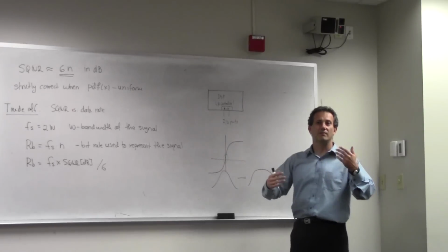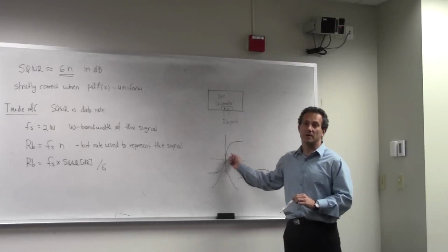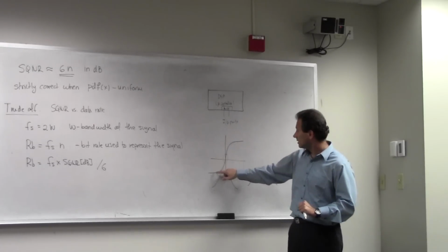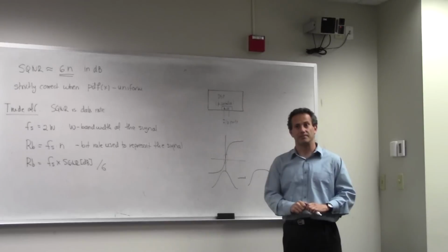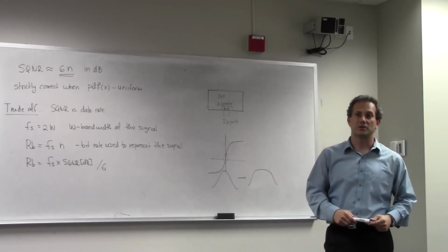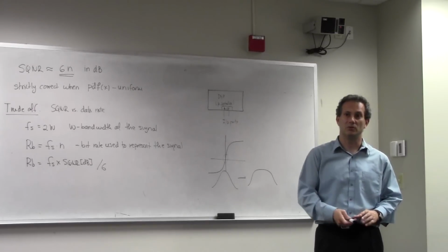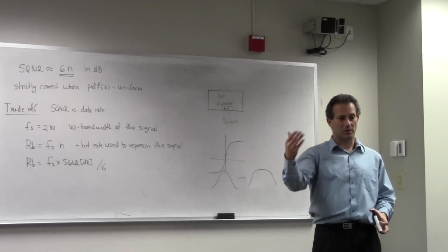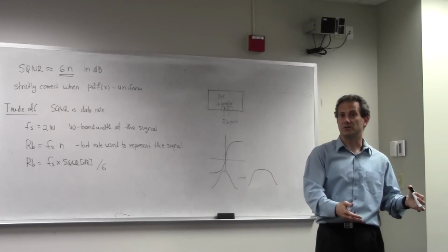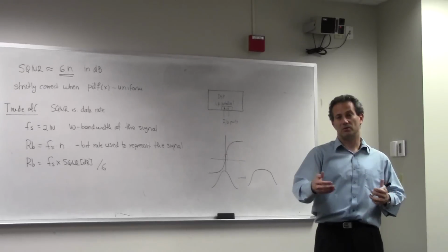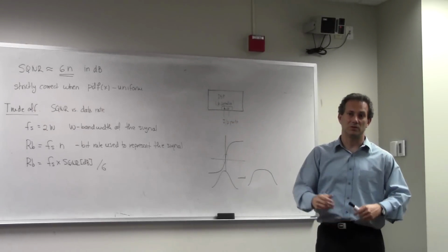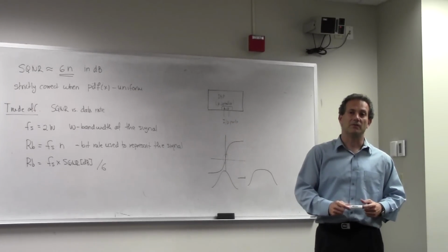Right. And we have these compressions for different signals. And this is what I'm going to talk about next time, how you actually design this and what is the optimum compression, and if you know the PDF, how do you determine the transfer function of this amplifier. So we don't build non-uniform quantizers? No, we don't. We build uniform quantizers, and then we have various compression techniques, which pre-process the signals before we feed them to the uniform quantizer. And maybe you've heard, I'm going to go a little bit ahead, you've heard about mu compression, A compression. These are the compressions that are used, for example, in voice processing. If you feed the voice to the mu compression, then you actually end up making it more uniformly distributed in the amplitude domain, and then we feed it to the uniform quantizer. And next time we'll see that there's significant benefit that you can get from it.